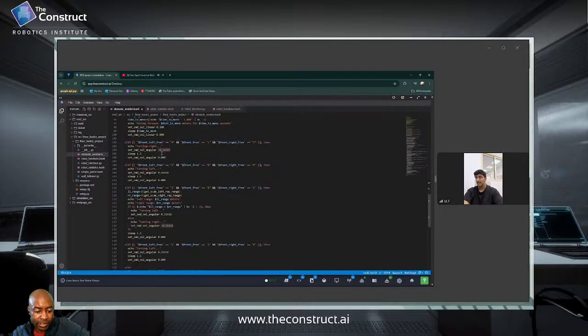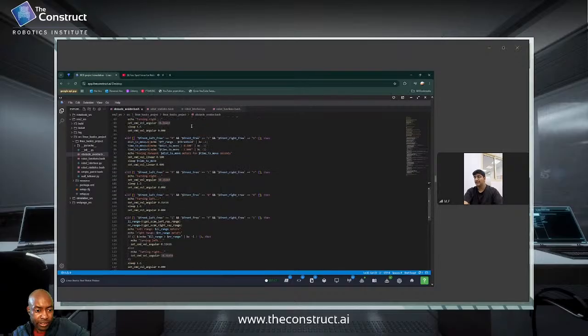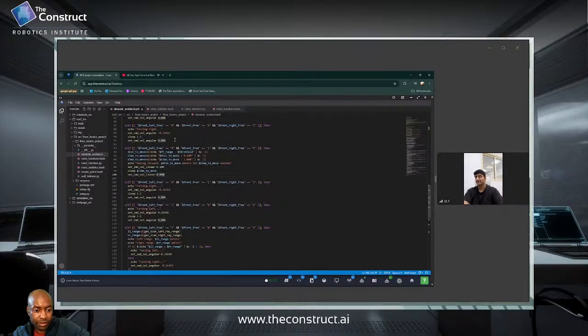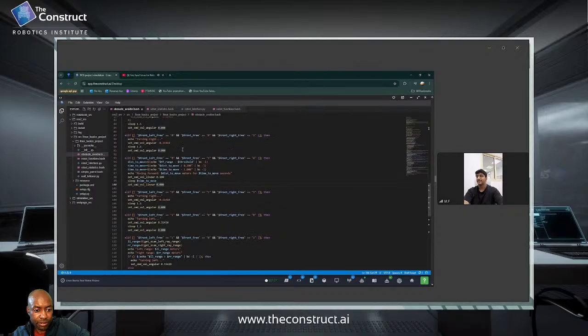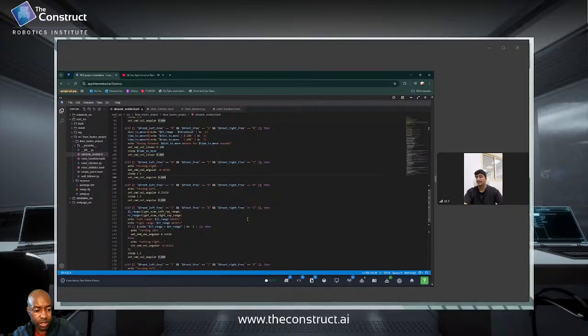Again, all of these else if statements over here are basically just there for the turning, for the left, for the right, for moving forward, and all those kinds of conditions. Because you can't just have a singular if statement that says, if you see an object on the right, then turn left. What are you going to do if it's in the front left, and so on? So I've just modified different conditions, because you can see 0, 1, 0, 0, 1, 1, 1, 0, 1, 1, 0, 0, basically testing every possible combination.